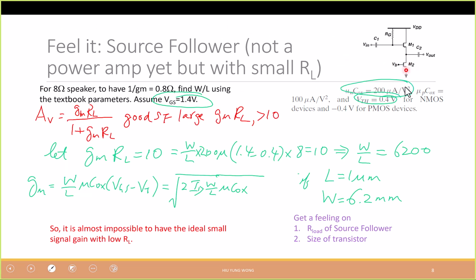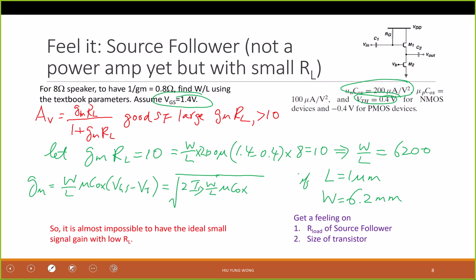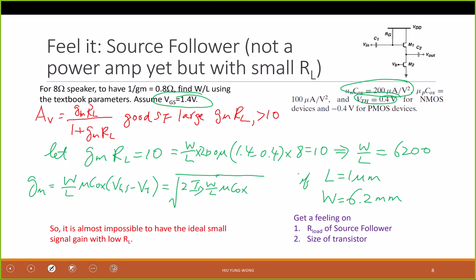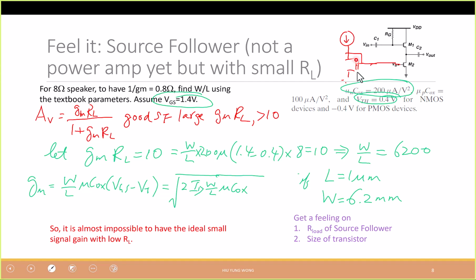You can come from a current mirror, correct? Current mirror, again, another hint, we studied current mirror, right? So you may bias this to something like this. You have a golden current source, right? Do you remember how to bias it? Instead of really putting a battery with VB, we actually let this current mirror bias this one, right?